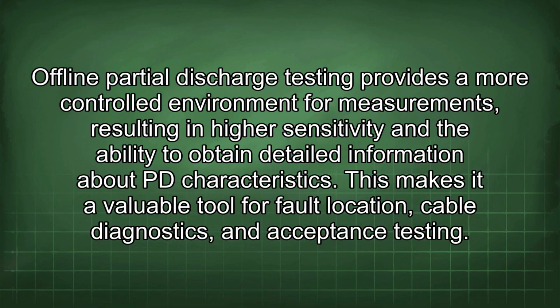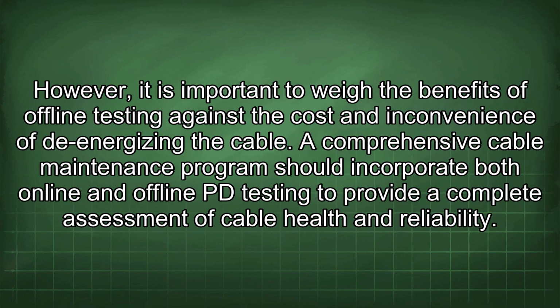Offline partial discharge testing provides a more controlled environment for measurements, resulting in higher sensitivity and the ability to obtain detailed information about PD characteristics. This makes it a valuable tool for fault location, cable diagnostics, and acceptance testing. However, it is important to weigh the benefits of offline testing against the cost and inconvenience of de-energizing the cable.